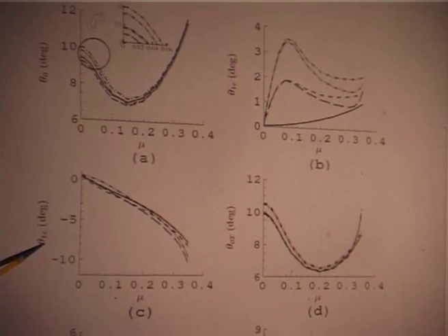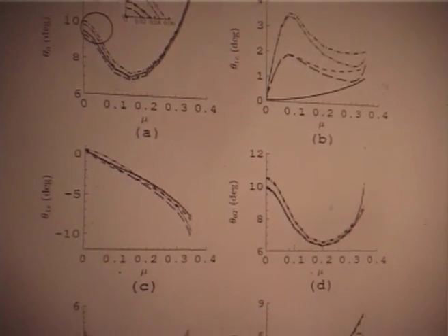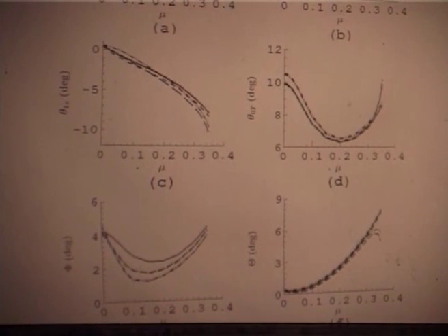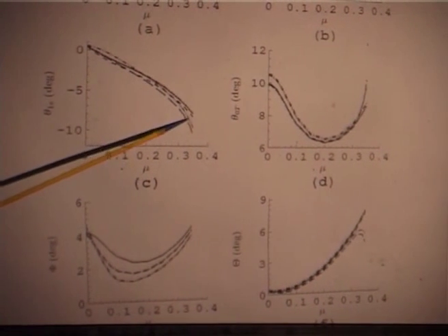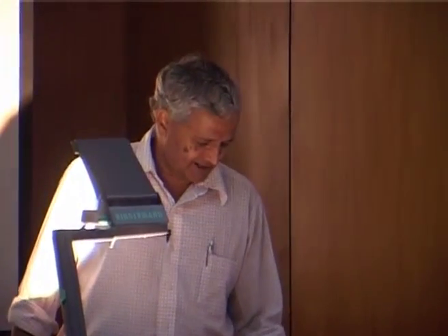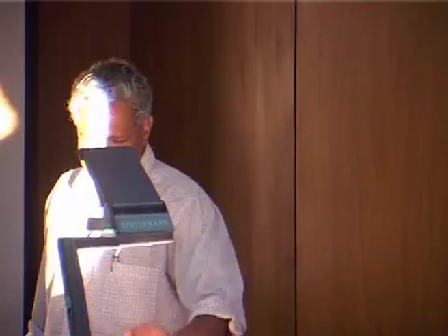Cyclic, that is theta 1s, which is directly related to beta 1c. They go up to minus 10, minus 20. So, the pitch angle can go to very high values in the retreating blade. Now, I just want to show this result, because this also we presented and